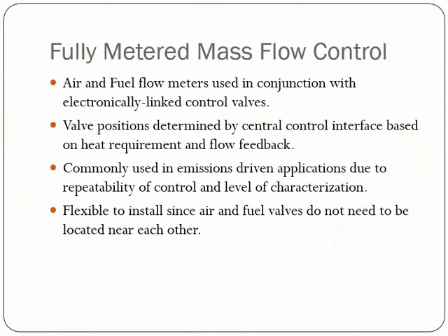So depending upon your chamber conditions or any other outside influences, that may be 45 degrees, 48 degrees, 47.2 degrees. It'll continue to adjust and maintain the flow and not just stay at that current valve position. So it's always looking at flow feedback and maintaining the flow as opposed to maintaining position.